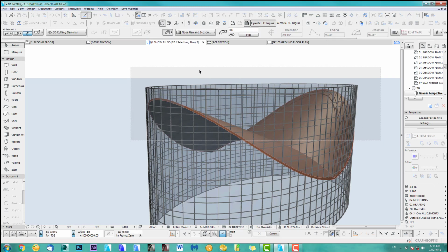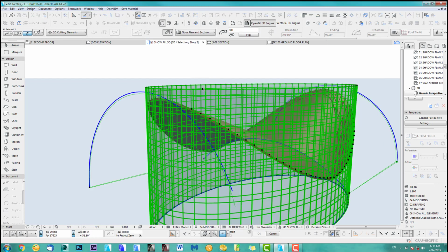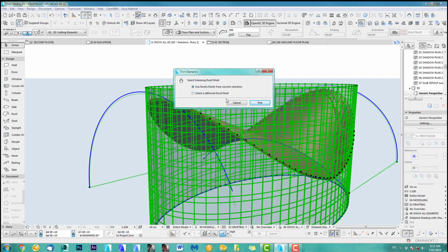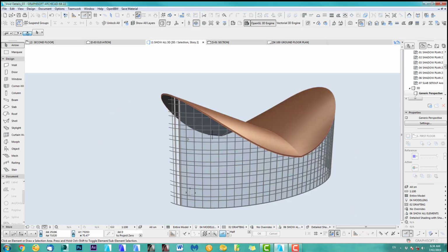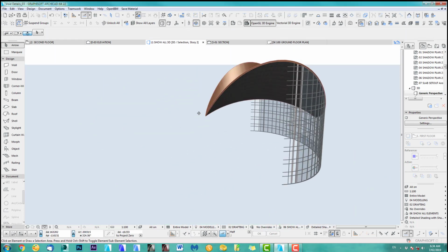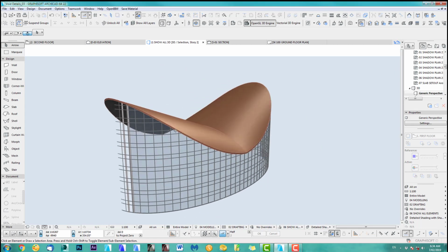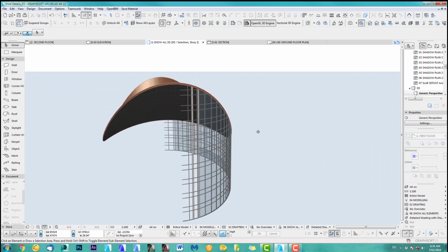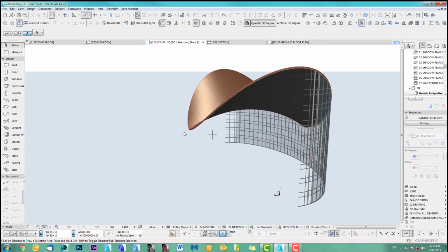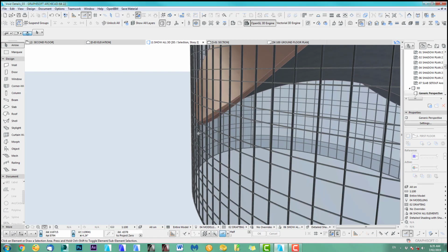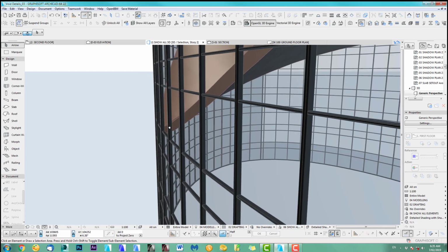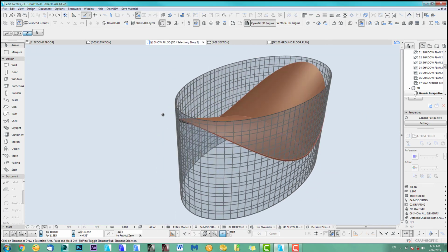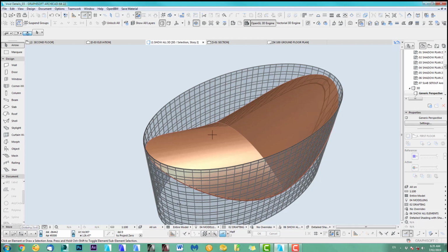Alright, select all of this. As you can see, it is a little bit slow with the curtain wall, even the selecting bit. And you just cut this off. Now if this happens, because it can happen, the curtain wall was outside of that roof, so it overlaps here a little bit, but on the other side it didn't overlap. So let's do another step. We have just to extend the shape of the shell tool slide. You can see it's not overlapping. So yeah, you just got to do that quickly, not a problem.